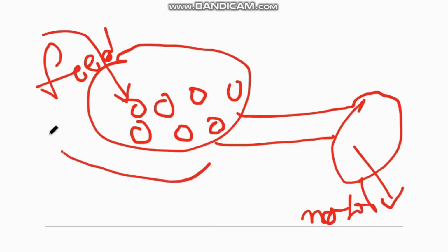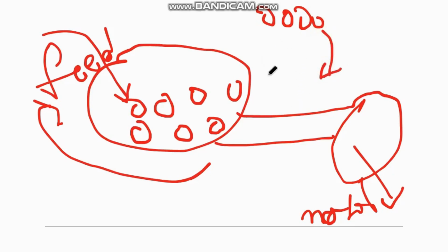Due to rotation of this cylindrical vessel, the balls present in it get lifted up to the upper position, and they come down due to gravity. So this type of action will cause impact. This lifting up of the stainless steel balls and coming down due to gravity will cause an impact effect on the feed.